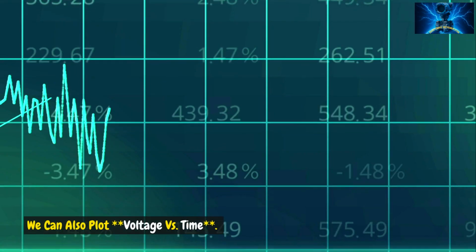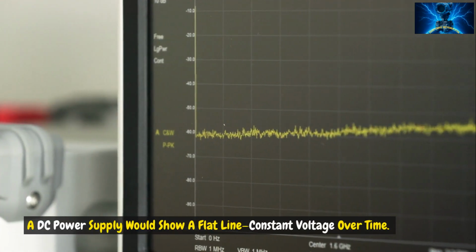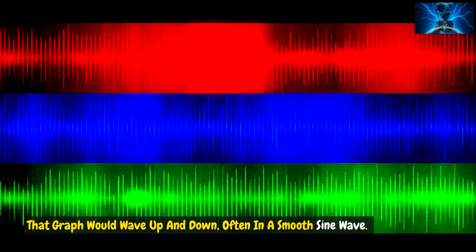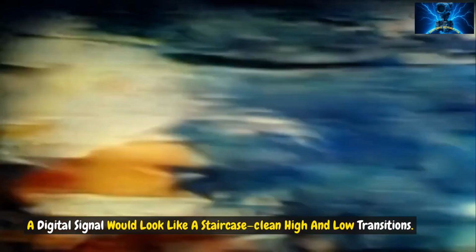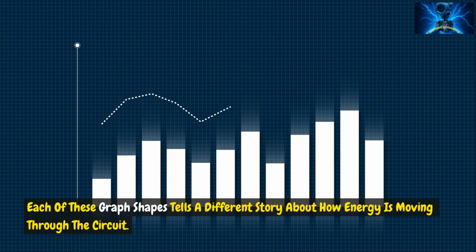We can also plot voltage versus time. This is especially useful in circuits with AC power, pulsed signals, or digital logic. A DC power supply would show a flat line, constant voltage over time. But an AC signal? That graph would wave up and down, often in a smooth sine wave. A digital signal would look like a staircase, clean high and low transitions. Each of these graph shapes tells a different story about how energy is moving through the circuit.